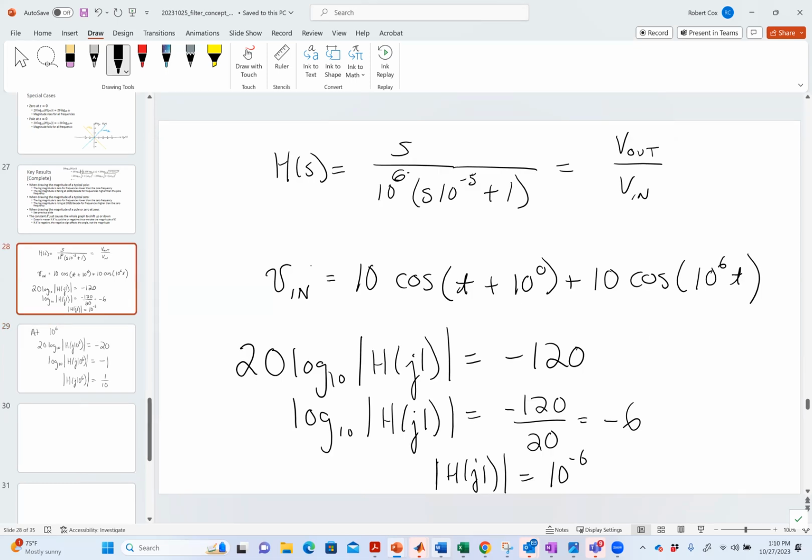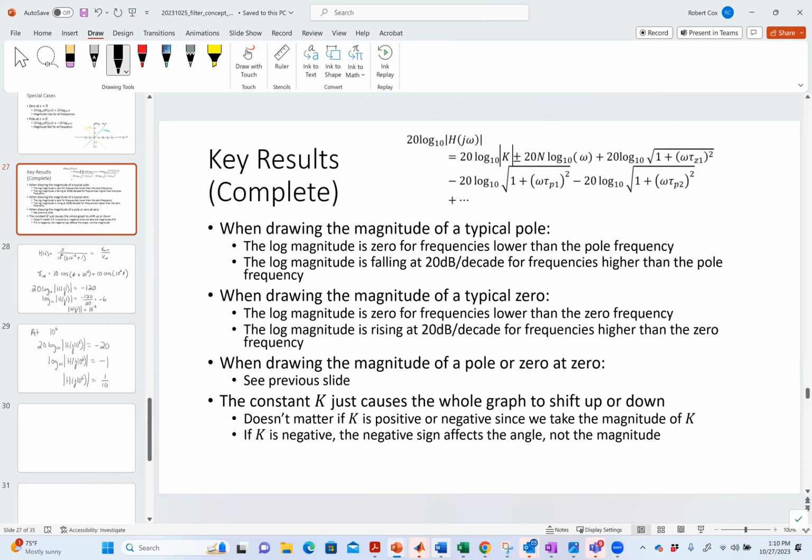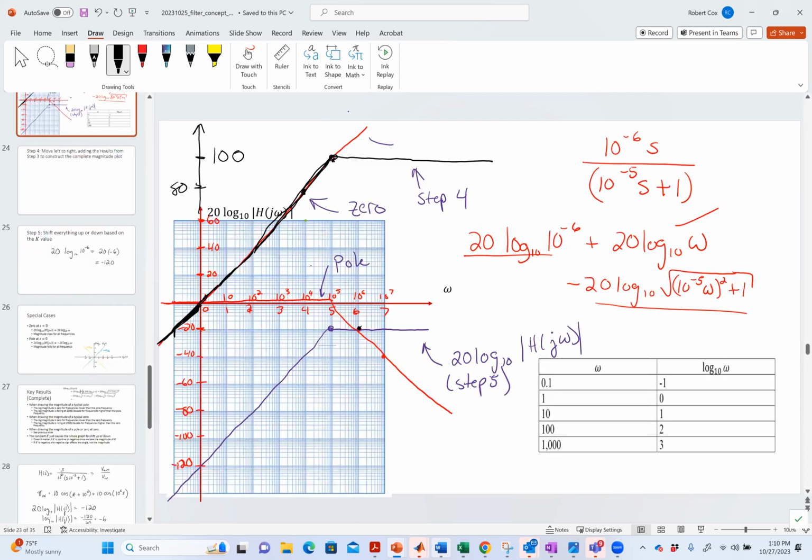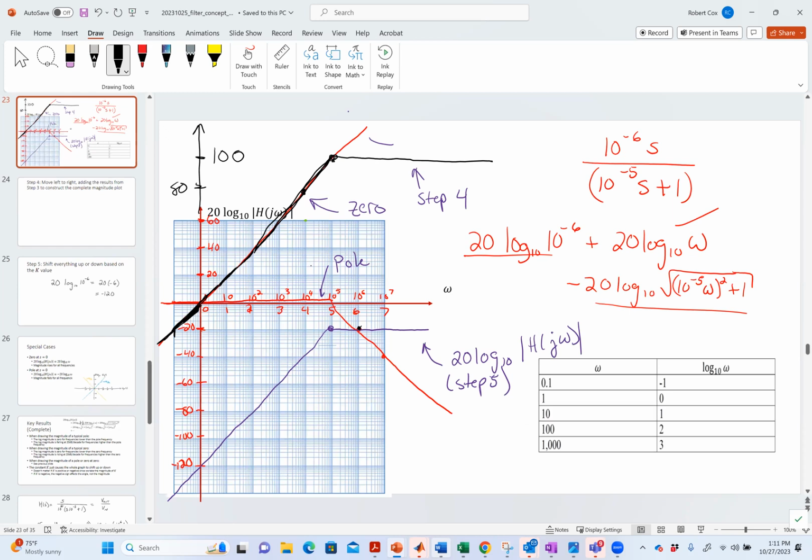So what kind of filter would this guy be? What has he done filter-wise? It's a high pass filter. He's making the low frequencies 0, and he's making the high frequencies a little bit less than what they were.